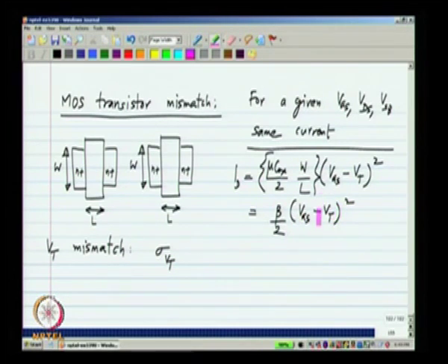Okay. This is because the nominal value of Vt could be 0 or very small. Okay. So, it does not make any sense to normalize it to the nominal value of Vt. We will see that it is nothing but just the sigma of Vt1 minus Vt2 for each pair of transistors. Okay. And this is a quantity that has dimensions of millivolts, unlike the mismatch in resistors and capacitors, which were relative mismatch and were dimensionless.